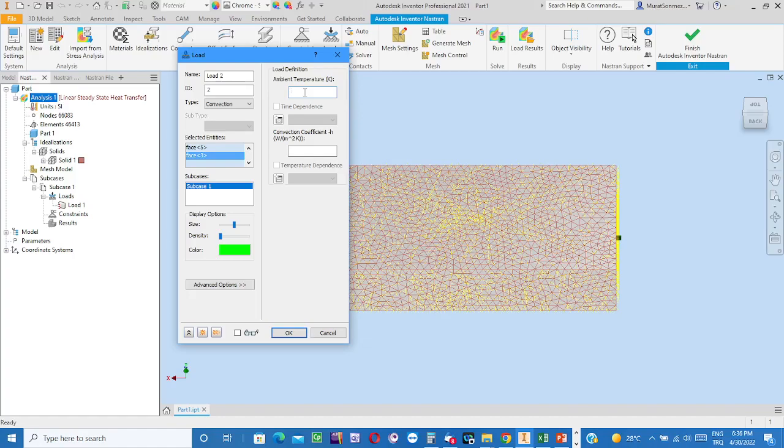and then say in this example the outside temperature, surrounding temperature, free stream temperature is 20 degrees Celsius, let's say, plus 273 is the temperature value in Kelvin. Okay, it makes 293 Kelvin. That is the ambient temperature. Okay, convection heat transfer for the vertically oriented surfaces, heat transfer coefficient is 20 watts per meter squared Kelvin.